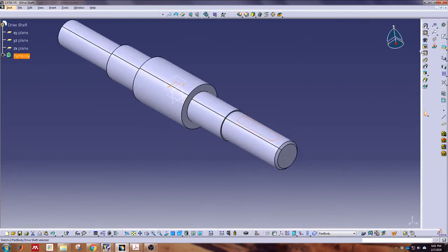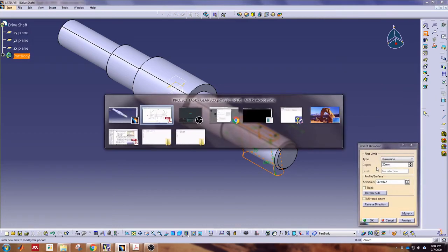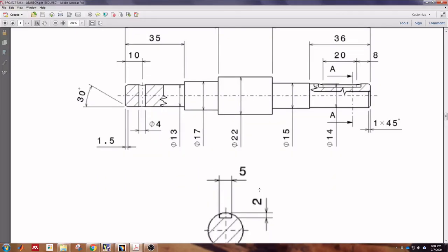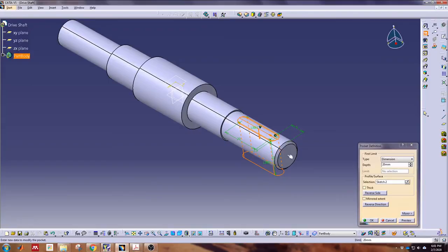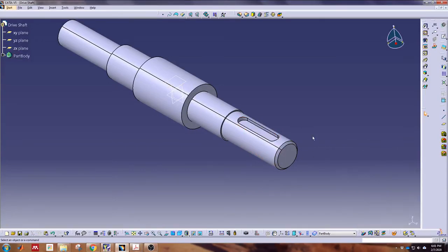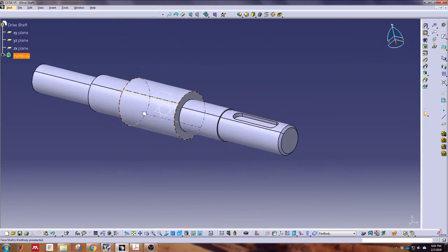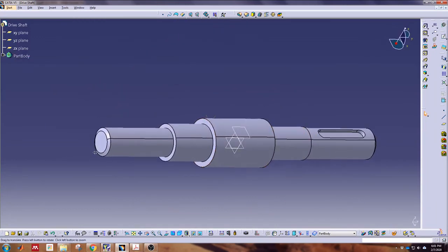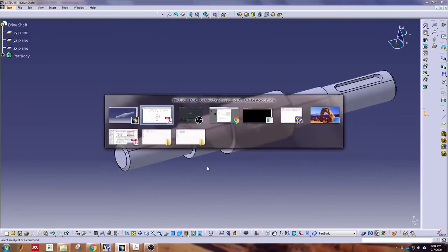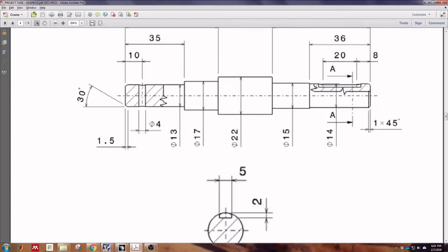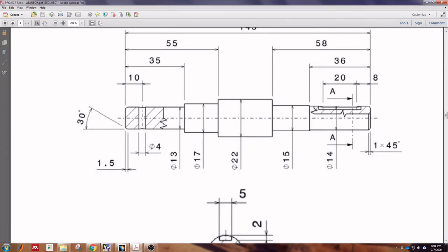Right, from there we can create the pocket, and the depth of the pocket will be only 2 millimeter. So change to 2, click OK. So we have finished our keyhole there, and what we need to create now is the hole of this bolt.